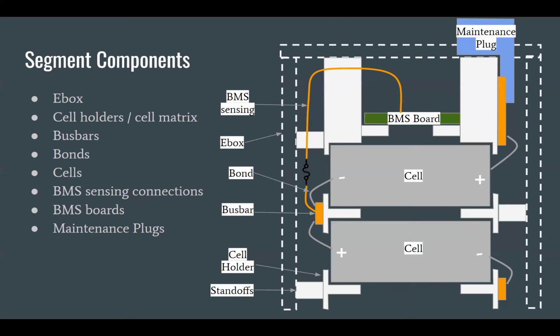But ideally, in the future, we would be able to take all these factors into consideration and say, okay, maybe we shouldn't design packs that have thick bus bars like this, and maybe we should design packs that have bolted connections that are sunk in, so that we don't have to deal with the bolts sticking out like that.